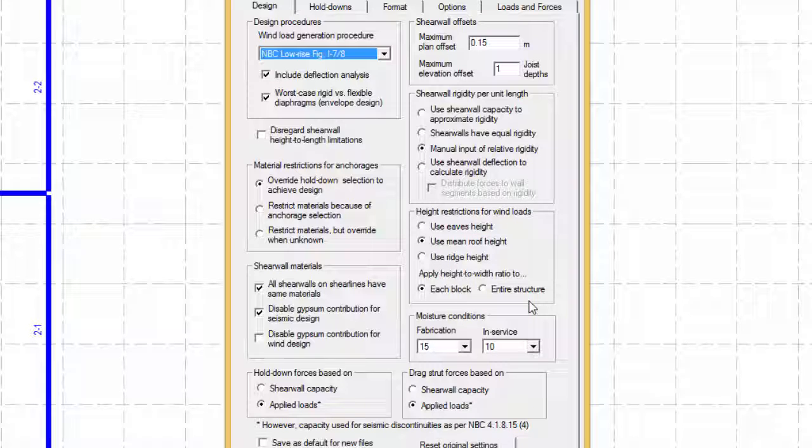A choice has been added due to the fact that there are currently no other method available for roof block structures and shear walls other than to use the all heights method intended for flat roof structures, which may not be the case for the structure the user is designing. This allows the user to apply to his or her discretion what reference height should be used.